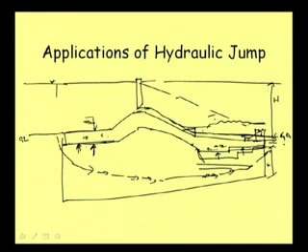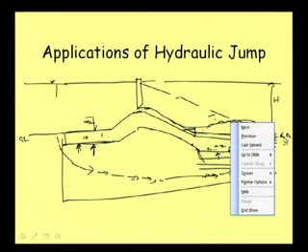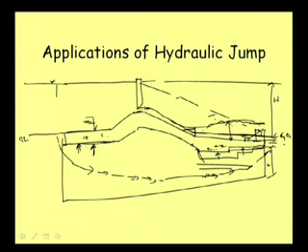So, this part is supercritical, that is subcritical. When it is rising, a hydraulic jump is there. So, the depth of water on the apron is also increasing. So, uplift pressure can now be counterbalanced, and that way the requirement of putting additional thickness to resist uplift does not come into consideration. Well, so again some other problems are associated with this.